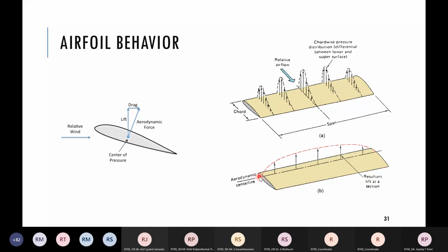Now, as the relative pressure at the end is 0, the lift force is going to be 0. Okay, so it has some parabolic shape. If we want to consider a uniform lift, then we can take an average. Then our average lift force would be like this straight line. So that is a simplification of our actual practice. Fine.